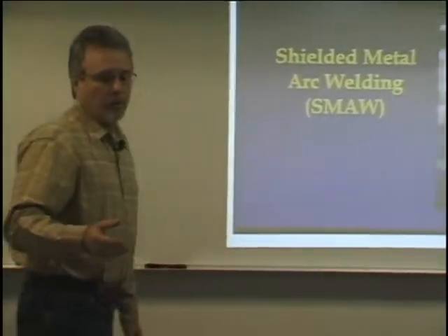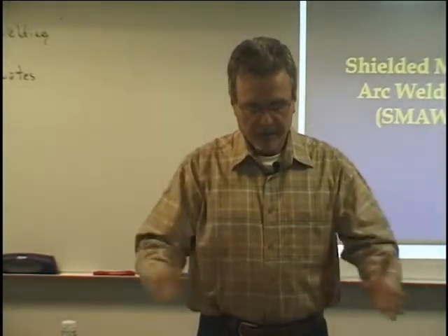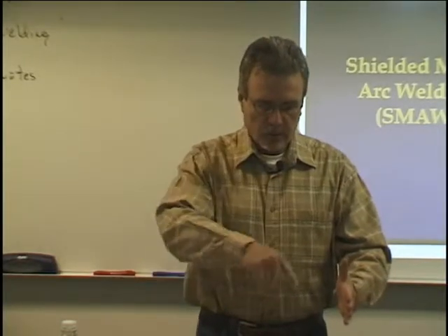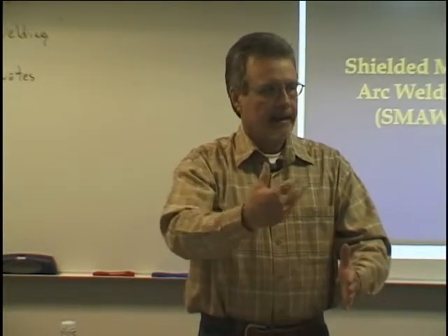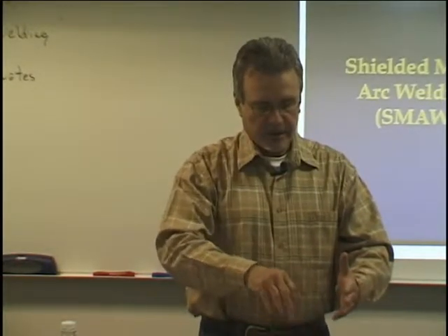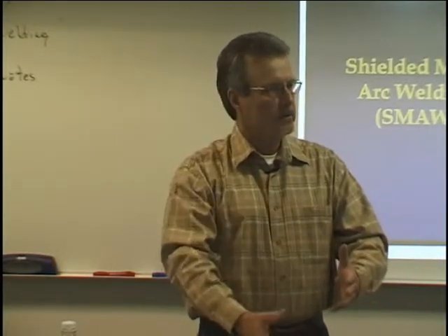As we get to that, I'll put up a slide of electroslag, but essentially what it is, it's a casting process. They'll take copper shoes and start a weld in the bottom, and they feed wire into it and use an electric arc to initiate the process. Then the slag, the flux that they put in there, becomes so hot through a chemical reaction that it melts all of that metal.